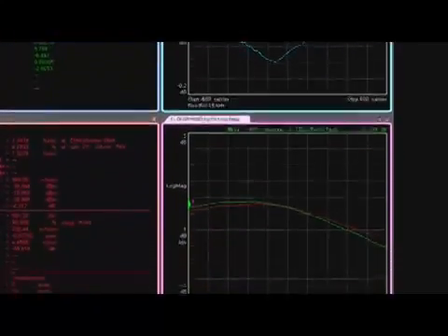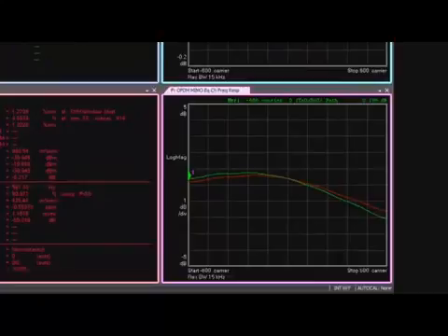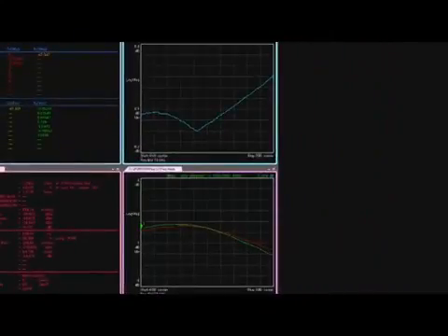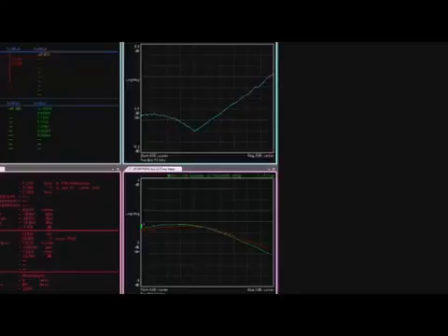This display shows the frequency response for each of the signal paths. This can be another aid in troubleshooting system problems. Compare this display with the condition number graph. It can be seen that the condition number is approximately equal to the difference in gain between the two paths. The variable condition number is apparently being caused by a frequency-dependent gain mismatch between the two channels. This could suggest a mismatch in the two RF paths or amplifiers, rather than an error in pre-coding gain.